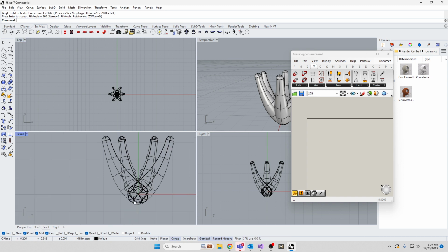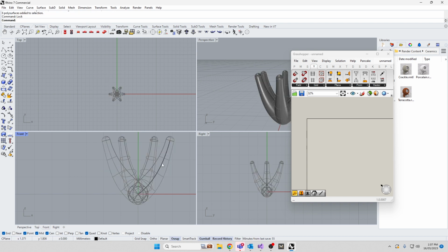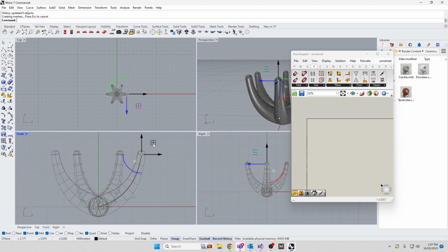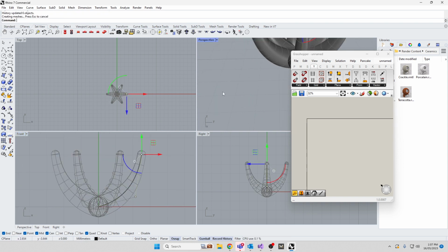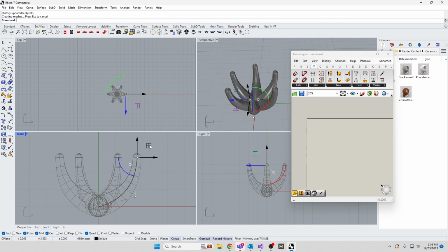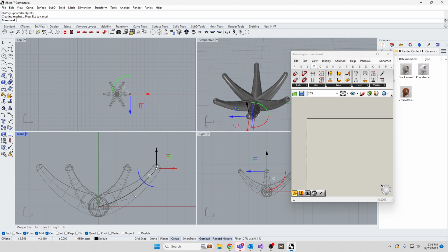So let's grab all these items and lock them down, I guess from there, not touching the curve. It means that you have a valid workflow where you can move this curve around using history, and you can quickly adapt this to different size collets as they come into run. What you haven't got is the ability to change the tip diameter here or here. You'd have to rerun the pipe command for that, or you'd have to build this very carefully with history to have a sweep. But when you move this over here, the circle for the sweep then moves with the curve, and it becomes a little awkward.